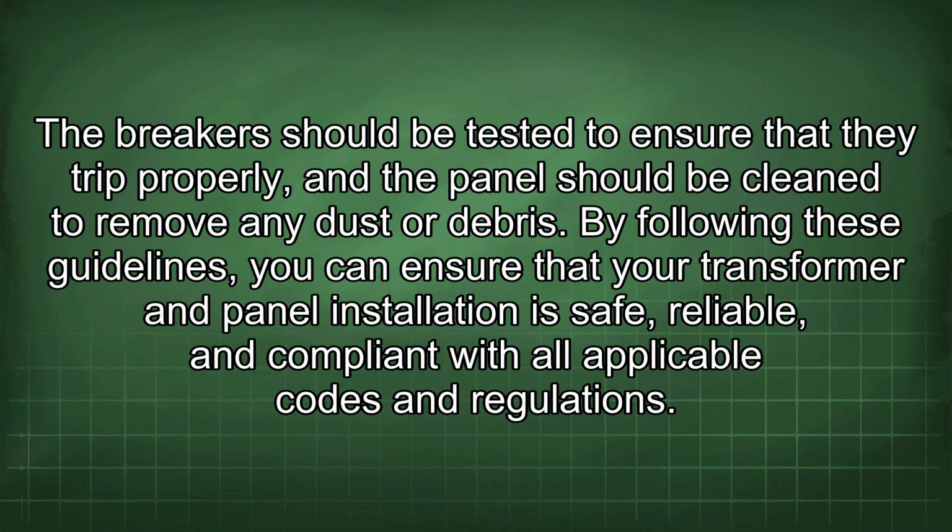The breakers should be tested to ensure that they trip properly, and the panel should be cleaned to remove any dust or debris. By following these guidelines, you can ensure that your transformer and panel installation is safe, reliable, and compliant with all applicable codes and regulations.